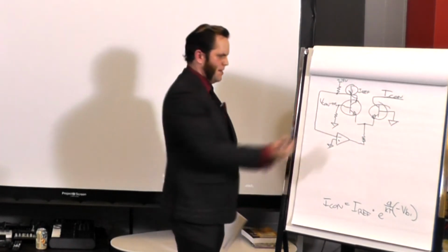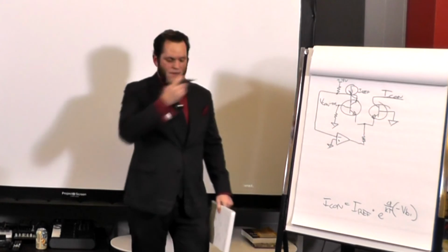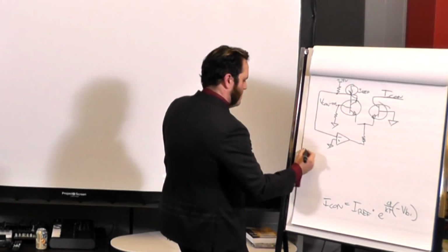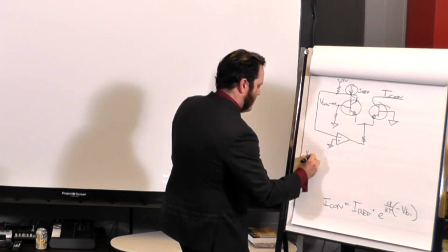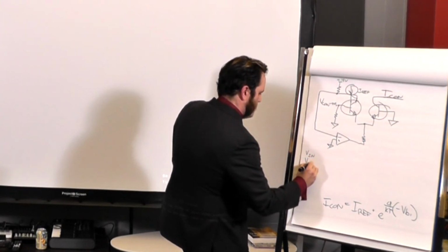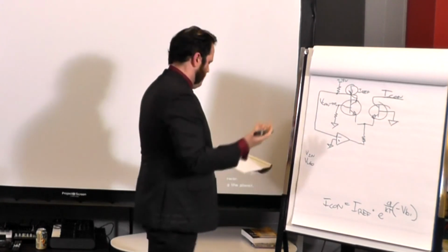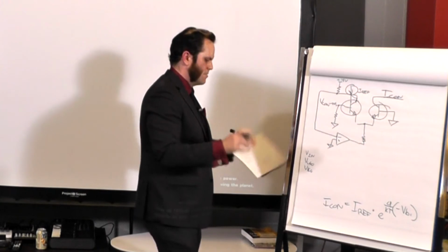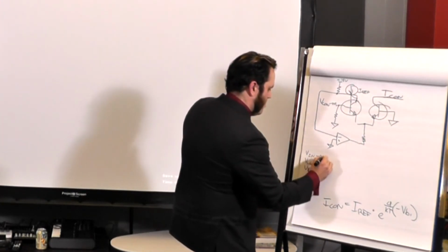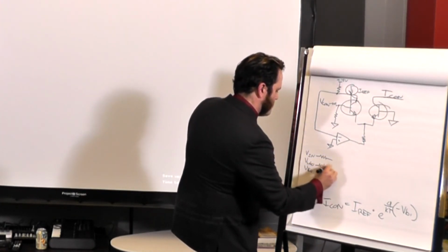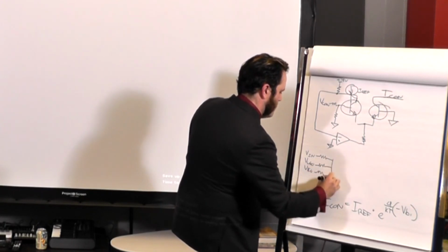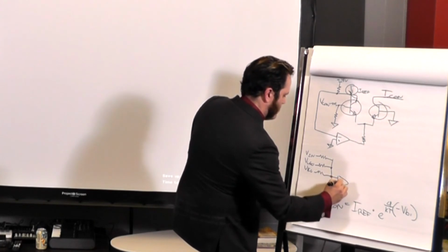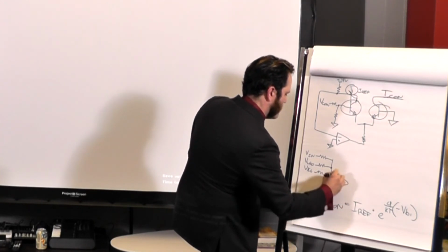So here's the other fun thing. I have this V control thing coming in, but I can actually mix a whole bunch of stuff into that. If I have some input from a keyboard, voltage in, and then some LFO voltage here, and maybe an envelope generator there that's giving me a cool attack delay response curve, I can mix all of those together. Throw that into a buffer real quick.